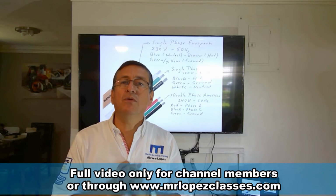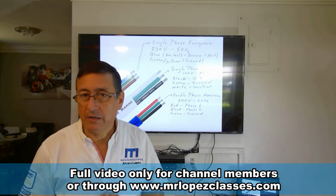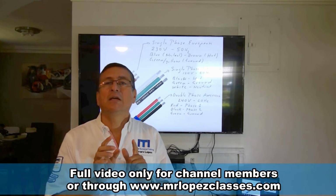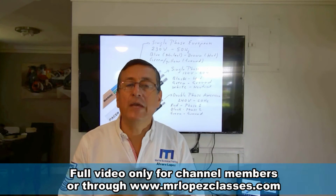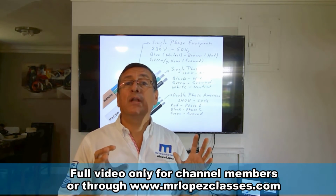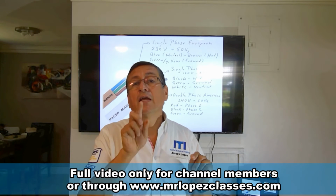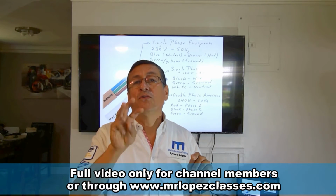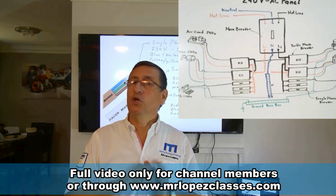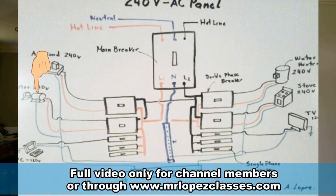The reference when you have double phase and three phase is with the ground, not with the neutral. The neutral is used for reference only in single phase. It's clear? In the future, if you want to connect a three-phase motor, you need to connect phase 1, phase 2, phase 3, and ground, no neutral. You want to connect a double phase blower, okay, you connect phase 1, phase 2, and ground, no neutral.